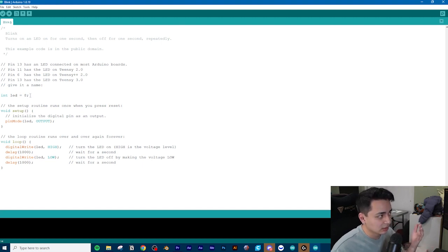That's basically telling the IDE that this line of code is over and to start looking for the next piece of code, right? So from here, there's sort of two different sections of code that you can program. So there's void setup and void loop that basically come by default in every new file that you create with Arduino. The difference is void setup means that you put anything in void setup that you want to run exactly once. As soon as you give the Arduino power, it's going to boot up and run all this code that it sees in setup exactly once.